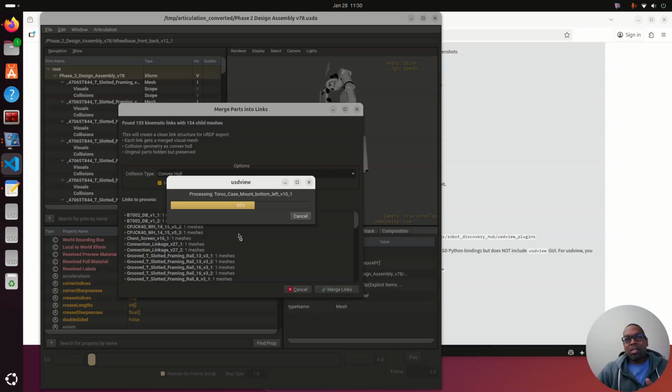They're just vastly different. And if you send commands in nanoseconds to move a robot's legs, those commands will be interpreted differently in the simulator than they will in the real robot. So we have to do that true up. And that's why you see robots hanging from gantries, because we have to get that timing correct.